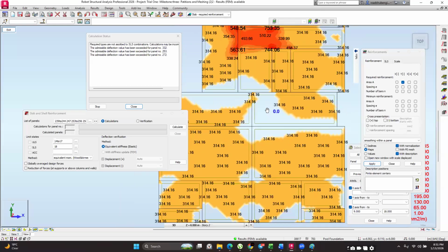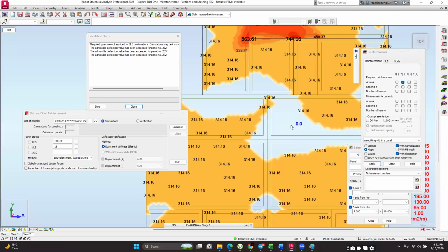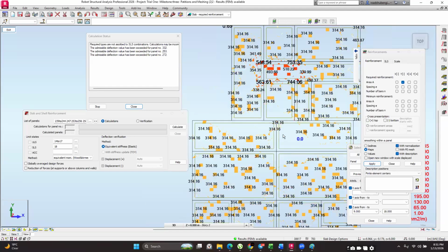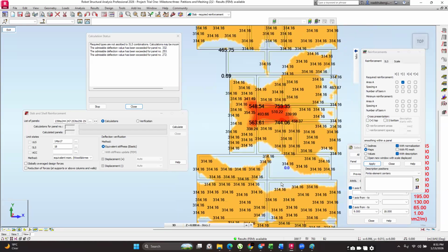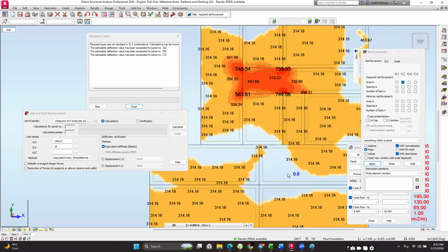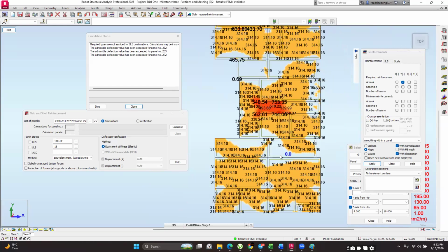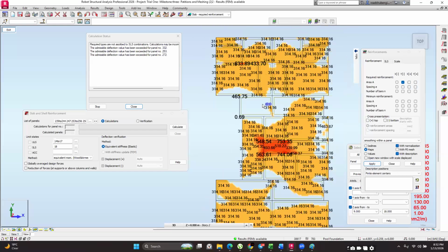So where you have these zeros, it means that no reinforcement theoretically is required here. That's why this is theoretical. Okay, so from how the software has calculated this, it means that theoretically in the Y negative direction, Y negative is this direction here, that you do not need a reinforcement at this bottom here. Okay, so this is just theoretical. It's just a good way of understanding how your slab is behaving, but you would not typically use this for anything but your detailing, just to understand the slab.